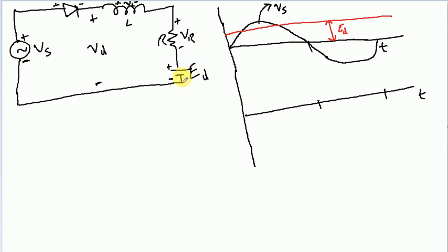In this particular circuit, the cathode terminal of the diode is at this potential. So whatever is the peak value of this voltage source, which I have shown over here by this color, is available at this terminal of the diode. Unless and until the input source voltage exceeds that value, it cannot cause the diode to become forward biased and start conduction.